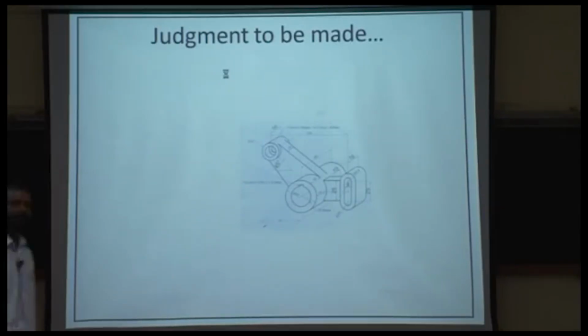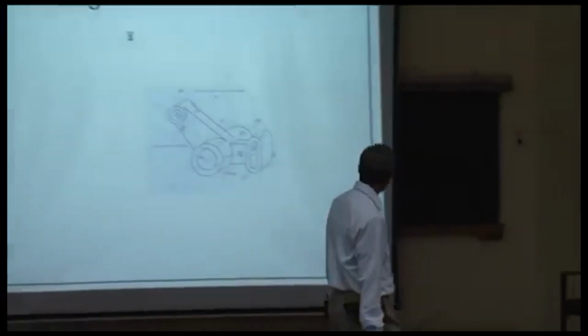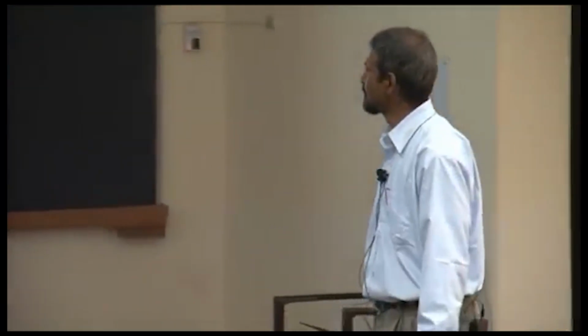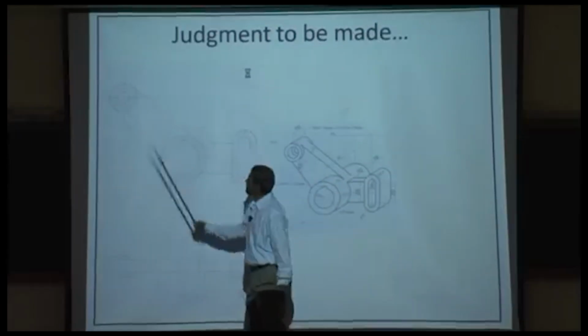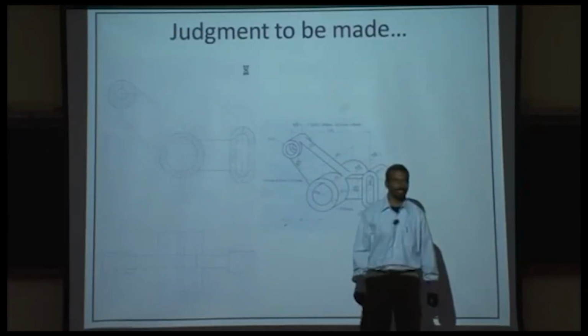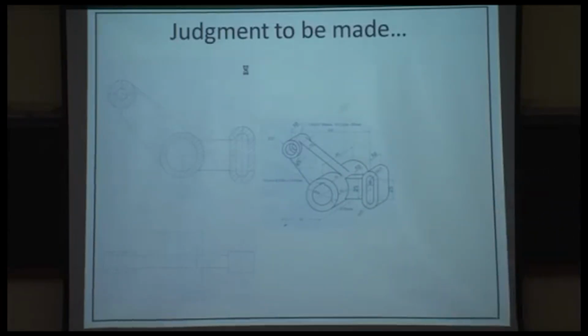I chose to depict them as ribs when I was working on the solution for this, so I didn't section them. I sectioned only the three main features: the center cylindrical feature, the top left cylindrical feature, and this one. I didn't section the two parts in question.